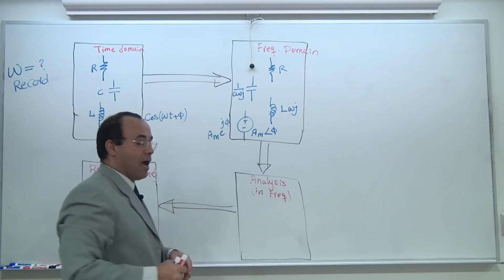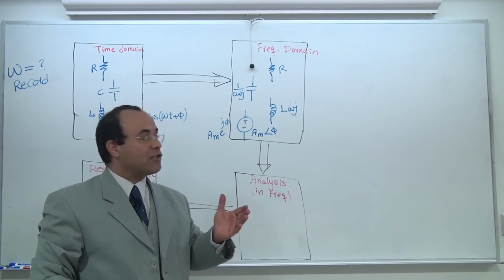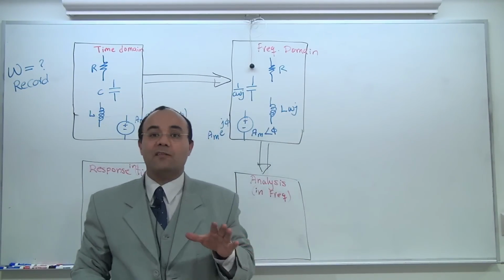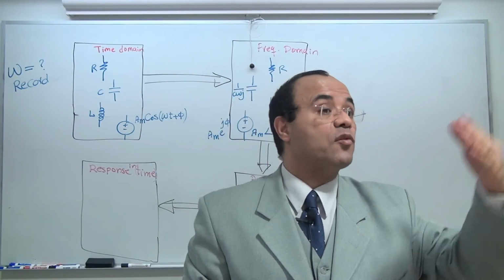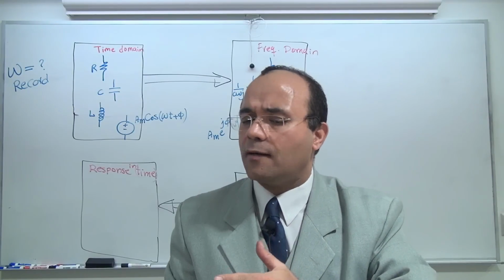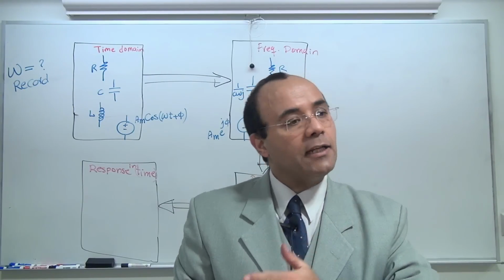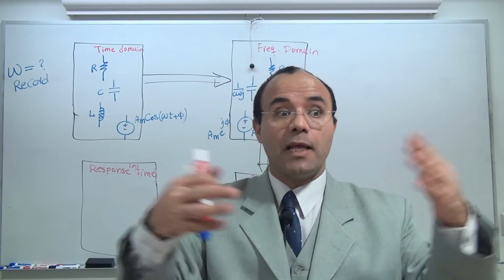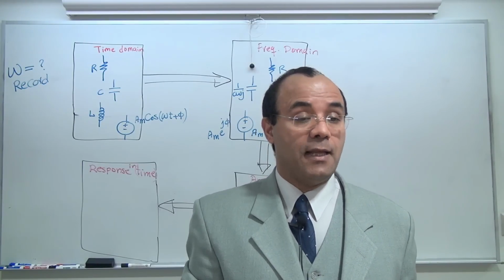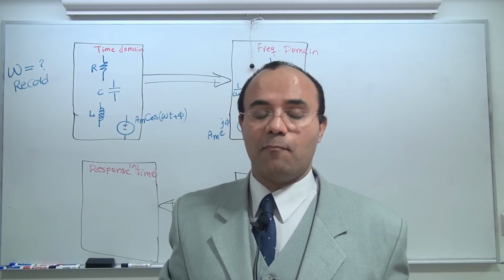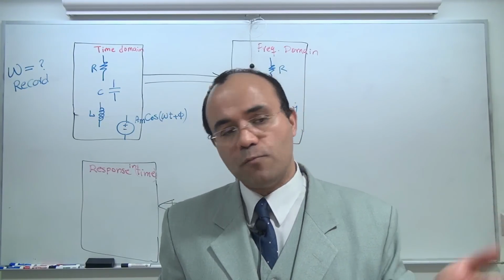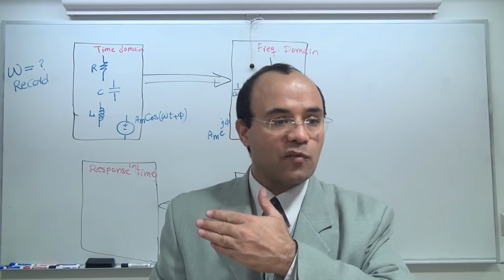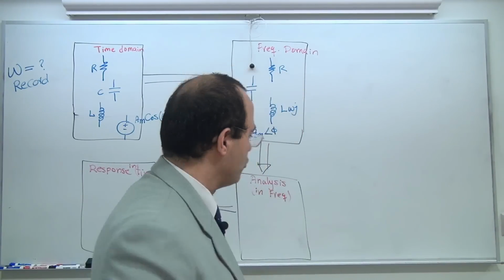Then, I'm asking you to imagine that your system now is resistive. Resistors are resistors. Capacitors are complex resistors. Inductors are complex resistors. But everything is resistor now. If everything is resistor, you can apply the same thing you learned pre-midterm. Do nodal, do mesh, supernode, superposition. Everything that you can do, please do.